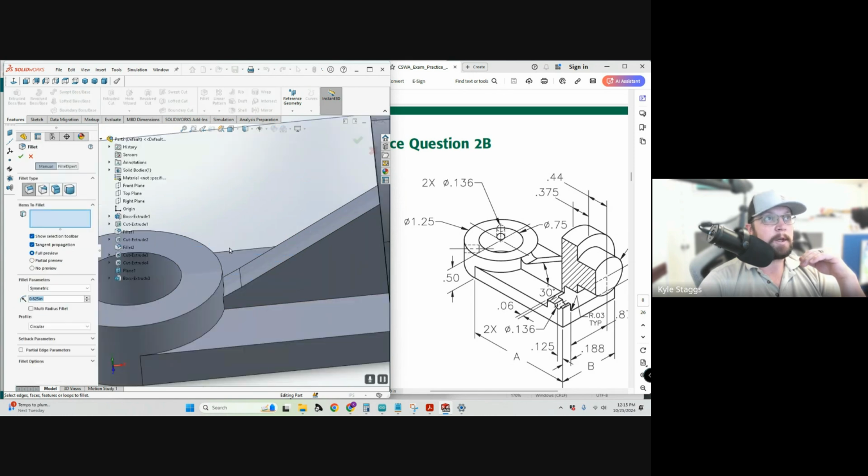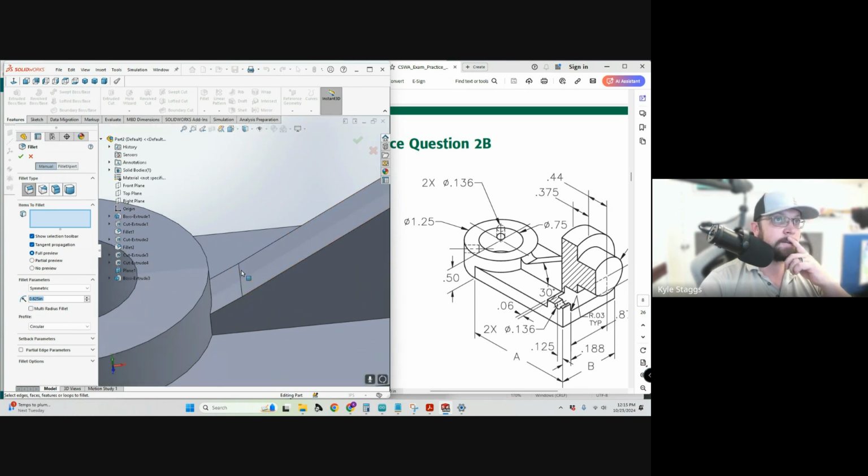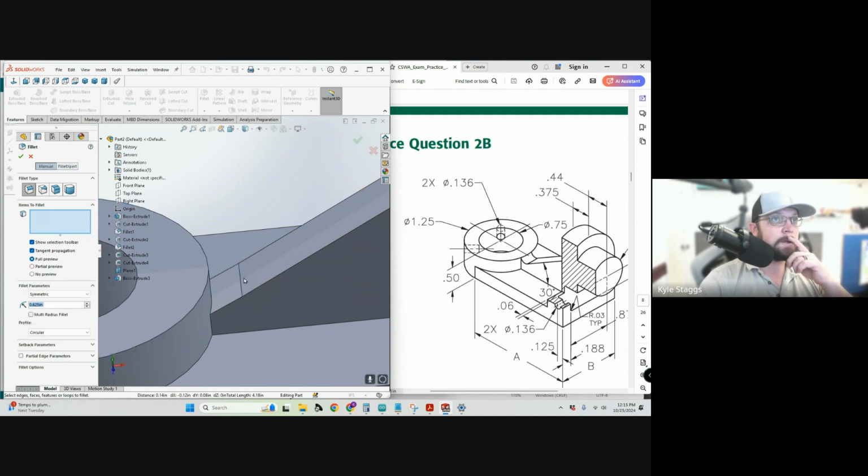This is one of the reasons why this particular part was dropped. We need to fillet this edge to this face, and that's very hard to do. So we actually need to select essentially this one and do a radius of 0.1. You can get here and it will fix the geometry.